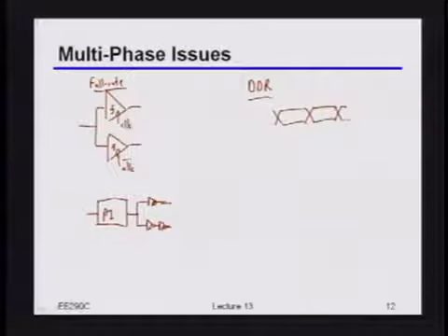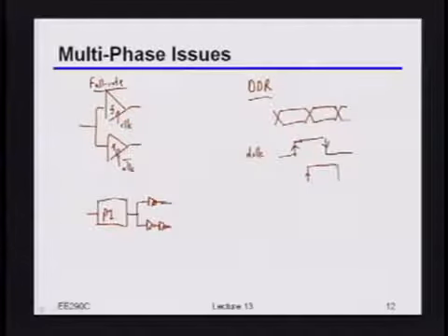If I look at my clock, I'm going to be capturing data both on the rising edge and on the falling edge of the clock. So this would be my data clock. Now remember, you still also have to do timing recovery, right? So that means I now need another clock that is 90 degrees phase shifted with respect to the first clock. Okay?